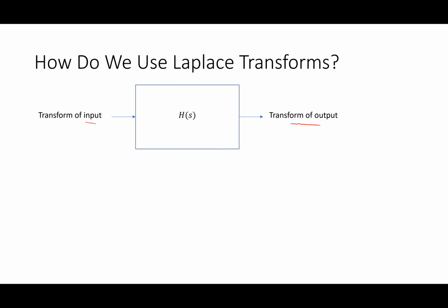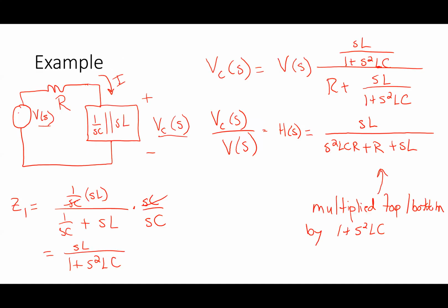All right. So the whole idea is I can take different things that would have otherwise required differential equations. We said differential equations are the right way to do everything. Bottom line truth: if I want to figure out what's going on in a circuit, it lives in the time domain, and so we have to do differential equations. It's annoying, so we moved to phasors. In the special case of sine waves, we can also move to Laplace transforms. In Laplace transforms, it became algebra, right? That's the beauty of it: I take the transform of the input, multiply it by the transfer function, get the transform of the output, and then I can inverse transform to get the time domain result. I'm not going to worry about that whole process so much.